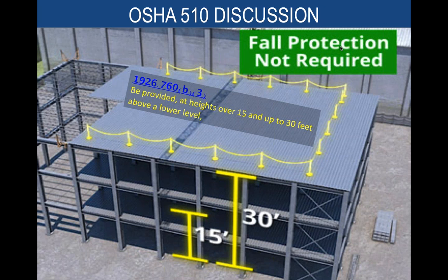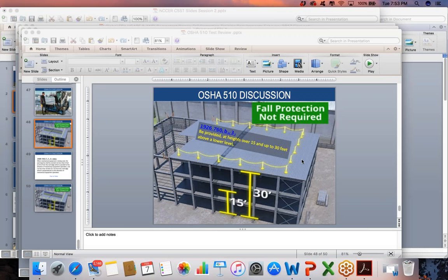Also inspect tools to ensure that the protective guards are in good shape. Also make sure all the safety devices are in good shape. Not using any powder actuated tools unless we're qualified and properly trained to do so. Powder actuated tools require their own certification or designation by the employer. So I'm going to show you that as well in just a second.